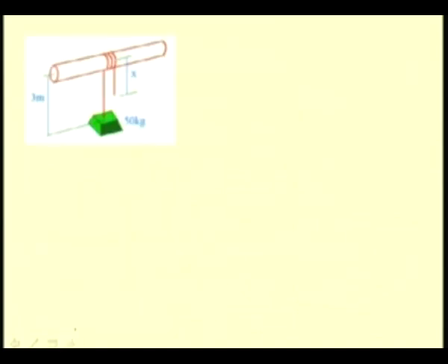Let us consider this diagram. For the equilibrium, the tension in this side of the rope and the tension in this side of the rope have to be related by the coefficient of friction and the angle of wrap that is occurring, in order that the equilibrium is maintained.